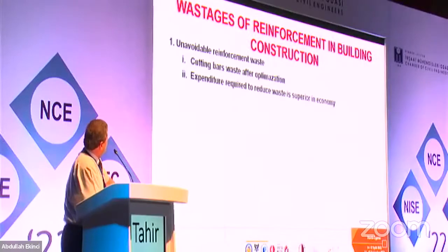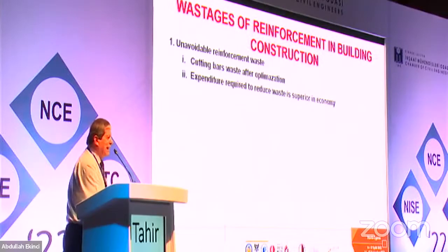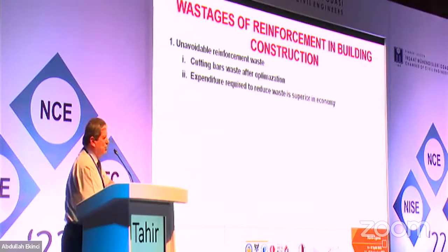If we talk about waste stages of reinforcement in building construction, there could be unavoidable reinforcement waste. What are those? Cutting bar waste after optimization. You can make an optimization, but still, because the length of the bar is the standard 12 meters, some length is unfortunately unavoidable and should be wasted.